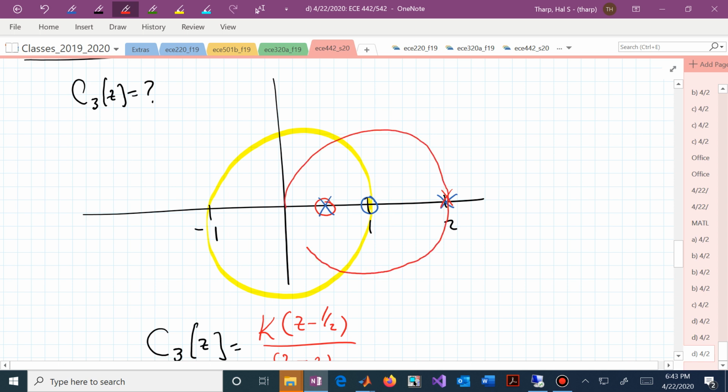That's supposed to be a circle. One goes towards that finite 0. The other one zips off to minus infinity. But now you can see that as long as our gain is big enough to get us beyond that square location on the root locus and stay to the left of star, we will remain stable.